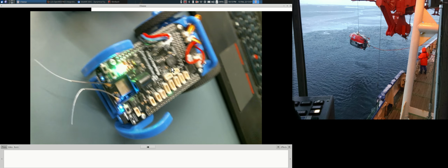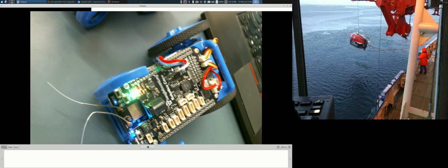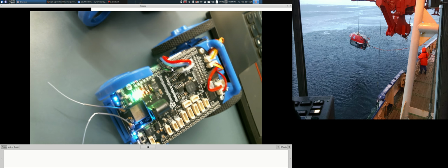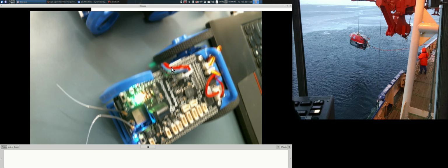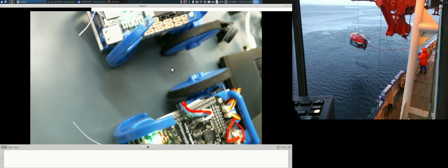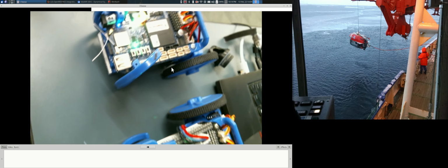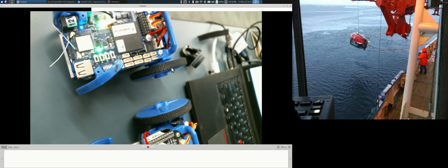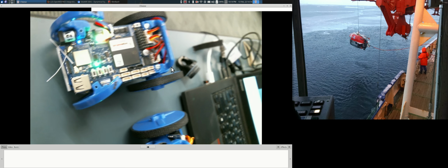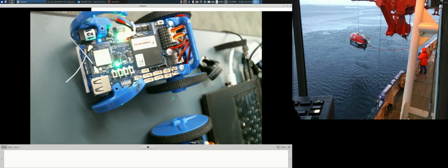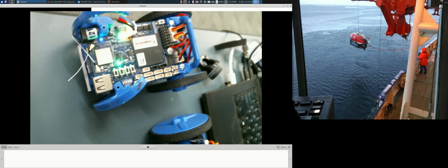So a good thing to do, in case I forget to say later, hopefully I'll remember when we're up and running, is when you're done using your BeagleBone for a session and you're about to put it back in its house and carry it around in your backpack, it's a good thing to power down the CPU with the command sudo poweroff. It'll ask for the sudo password, and then it'll power itself down.